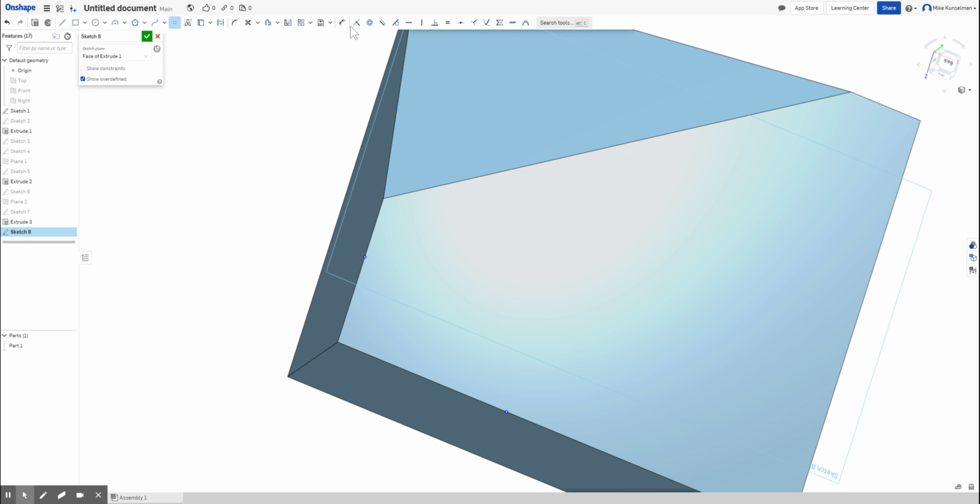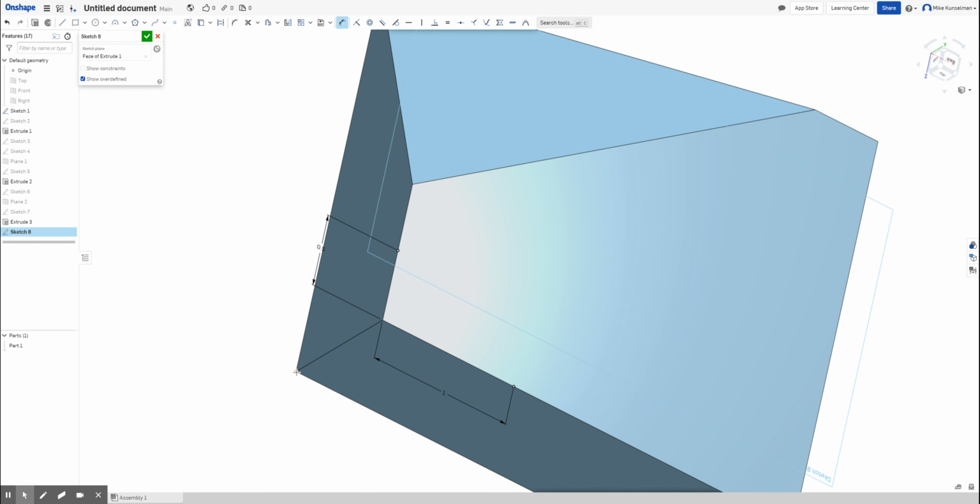Hi, Lucas. So what I'm doing is showing you guys how to make these clipped corners. Okay, so I put in 2 points. According to my drawings, it said that this point, so dimension corner to corner, oh, this one's in inches, so that's fine. Let's say it told me this one was half an inch up. We'll say this one is an inch away. Okay, so now I got these 2 points. If I was doing this full corner clipped off, I don't need to put a third point in here. I can just use what's there. If it was in a little bit, then I'd have to put a new point on another sketch over here. Okay, so I got those 2 points.